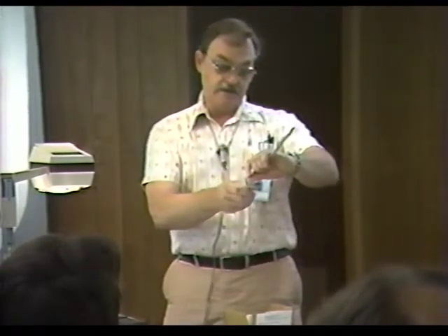This is just a handful of commonly used diode packages. In this shaped box, we're talking 200, 400 milliwatt sorts of things, 1 watt sorts of things, 5 and 10 watt sorts of things. As they get bigger, we'll mention Zeners here in a minute. If I get rolling, there's one at about 250 watts. And there's a rectifier that was, I wrote it on here because I knew I'd forget. That's 4,000 volts, 300 amps.